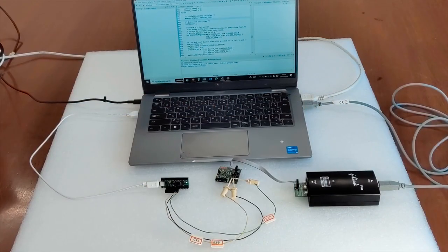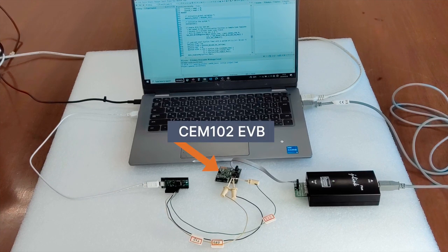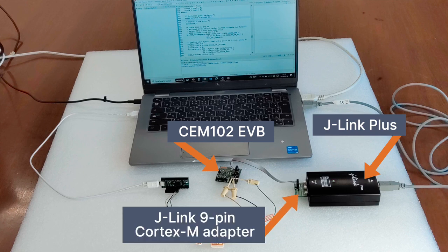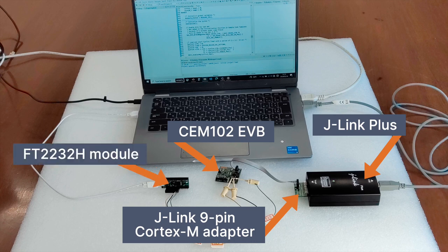To get started, you'll need the following required hardware: CEM102 Evaluation Board, J-Link Pro or J-Link Plus as JTAG adapters, and a 9-pin adapter cable and connector for J-Link. You'll also need a PC with USB ports and a power source for the CEM102 EVB. If UART monitoring is needed, please prepare an FT2232H module.